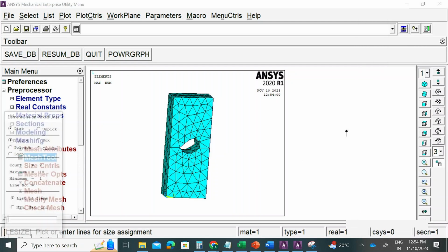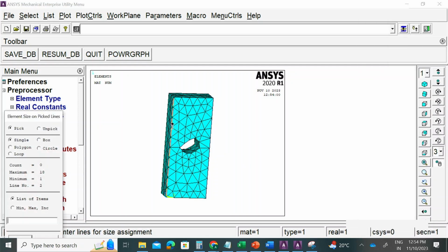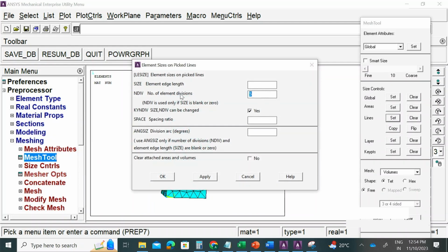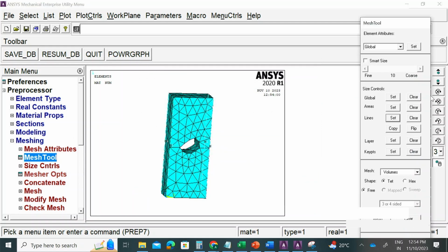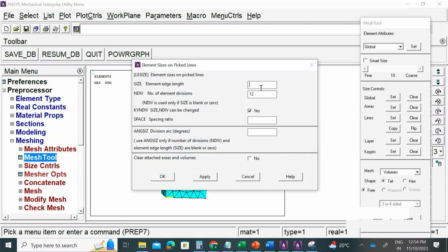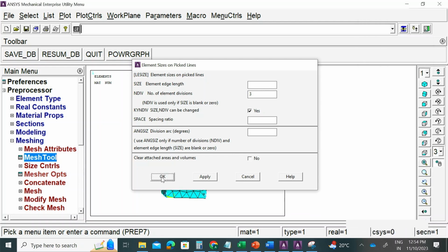So I'm going to reapply this sizing control, maybe make the divisions a little larger, 1, 2, 3, and 4. Maybe make them 12, right? And I want to apply the sizing controls here, 1, 2, 3, 4, 5, and 6. These are all similar. This can still stay, maybe 3, so 12, 3.